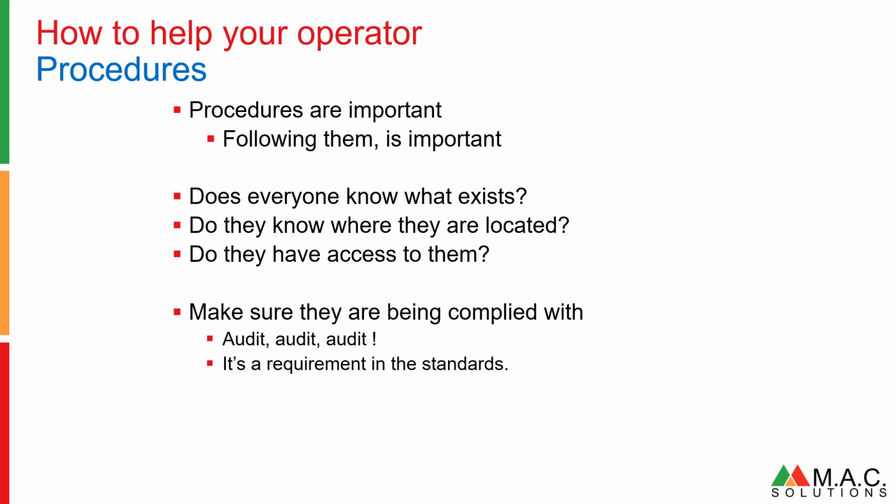I spoke to the control system vendor and asked his engineer, is there anything I can do? He showed me how to shelve them, and they don't unshelve at the end of the shift. That's a lot less hassle. This guy had shelved a bunch of alarms that nobody knew about, and that's not a good thing. Potentially, he's hiding alarms that other people are going to rely on. I'll get this alarm if anything's going to go wrong, and it's not going to happen. Potentially, you're hiding incidents. So make sure those procedures are being complied with.